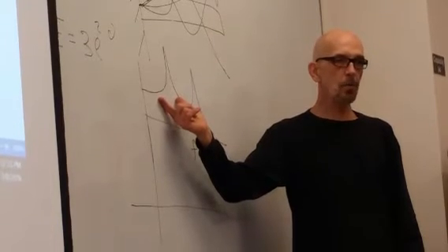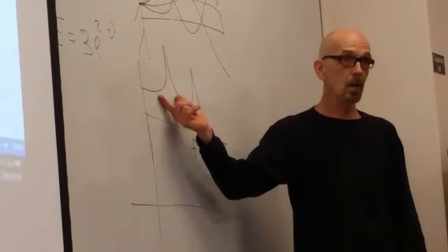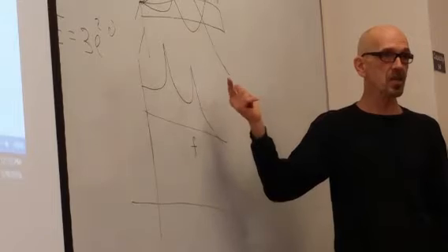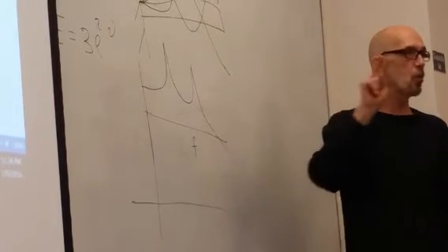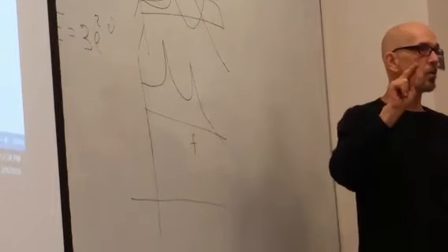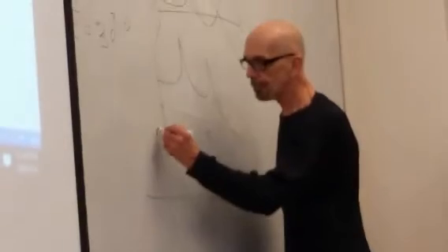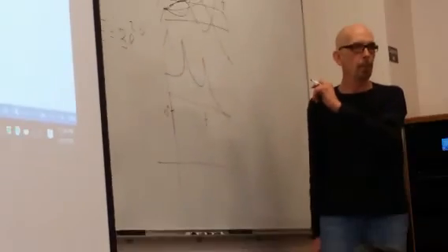C1 over s squared plus 2 zeta 1 omega 1 s plus omega n 1 squared, times C2 over the second, so it's 2 of them. There's 2 resonances in the system. It's a 4th-order system, right? Because each peak has to have 2 orders. It's an underdamped second-order system. So the phase would start here at 0, and if it were just 1, where would it end up?